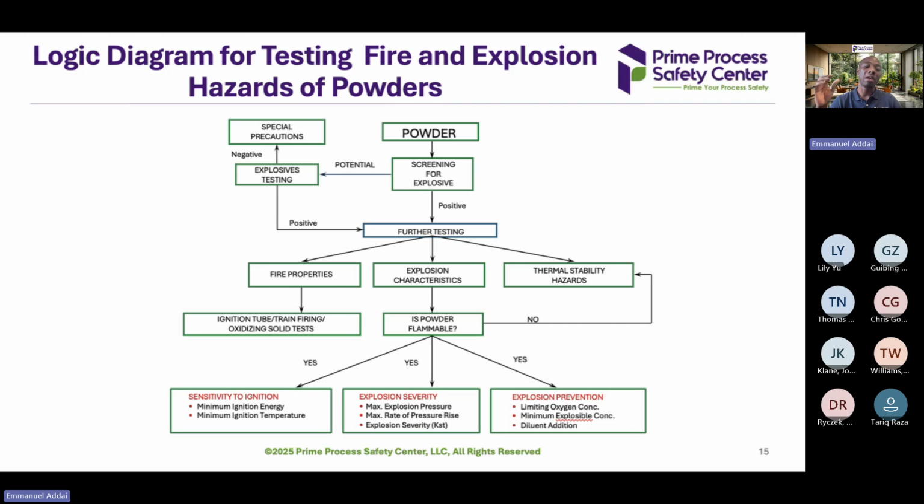And that is what every consultant thinks about before they actually visit a site or look at any operation. These are the thoughts that always come to mind. Is the material combustible? If it's combustible, how combustible is the material, what is the energy that can ignite the material, what is the minimum temperature that can ignite the material? What if the material ignites in a dust cloud, what is the maximum pressure it will release? These are some of the things that we need to consider.